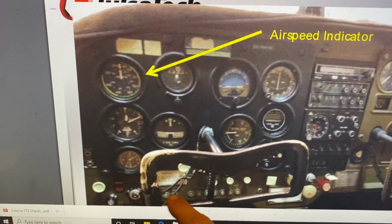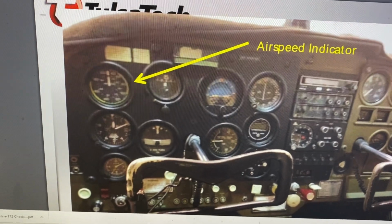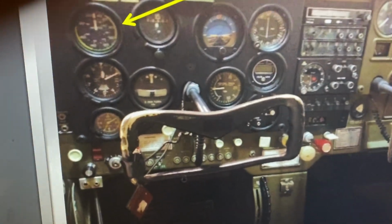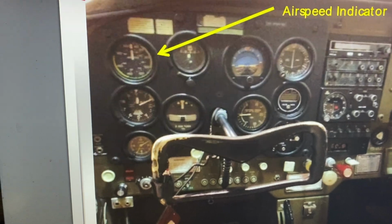Again, they're over here at the bottom of the panel. I showed you in a minute ago. Those are your circuit breakers. You want to make sure they're all in. Next thing you would do is push your mixture to full rich. So on this aircraft, you take that red knob and push it all the way in. That'd be mixture full rich.